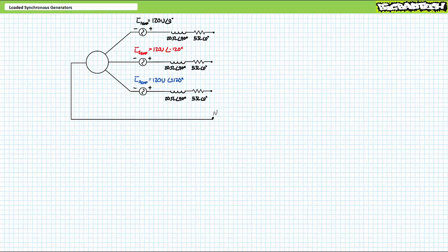Each stator winding can be modeled as a voltage source in series with a small resistance value, in series with a comparatively larger inductive reactance. The voltage source is the electromotive force produced by the generator when it's consuming the mechanical power of the prime mover. Thus far, we haven't output any electrical power, but this is where it's coming from.